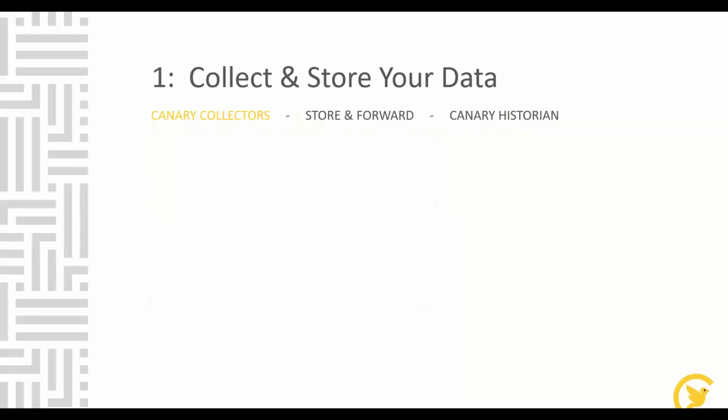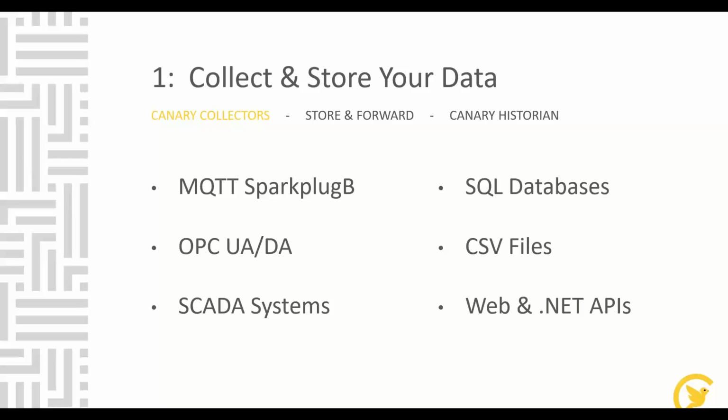So, collect data. Everything you need must be collected before you can really maximize the data. Canary comes with collectors that support the MQTT Sparkplug format, which is very much into the IoT environment, with the coming IoT trends, sensors, and platforms in the coming years. Especially we see a big jump when 5G networks are ready. But overall today, 90% of the customer base uses OPC-compliant UA and DA servers, and they also have direct SCADA system integrations developed through global partnerships.